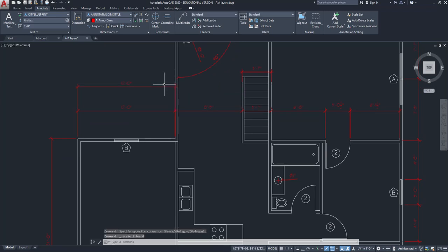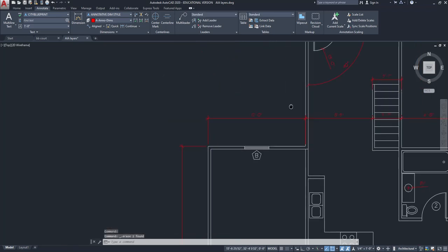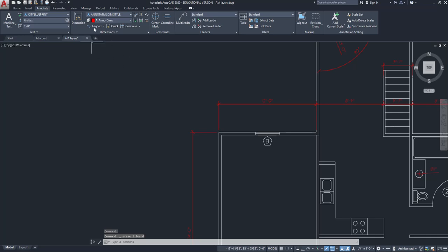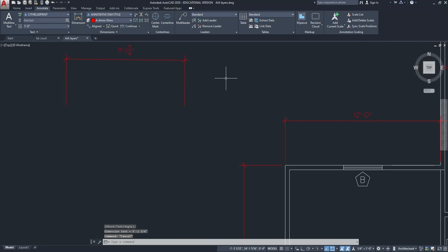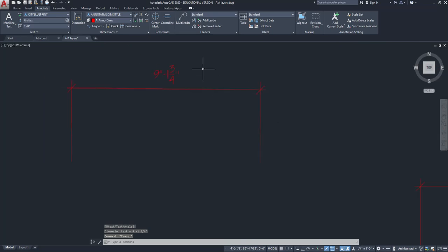Sorry, I said that was my final thing, but I actually have one more final thing I want to talk about with dimensions. This is just quick. I'm going to dimension in space here, okay? So I do have my dimension, looks wonderful. I have my text, I can click on it, I can move my text. We talked about that, okay? This little point down here, if anybody was curious, number one, if I select my dimension, I can click on that, drag this to wherever it needs to go, and that will change the dimension, okay?